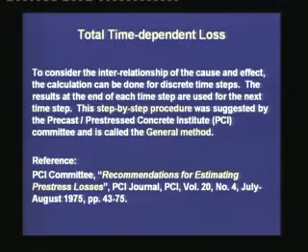Now, to consider this interrelationship of the cause and effect, the calculation can be done for discrete time steps. What we had seen before is that the phenomena of creep, shrinkage, relaxation are all dependent on time. But the estimates given in the code IS 1343 are simple estimates where the values are given only for the ultimate, and the time does not appear as a function for any one of the losses.